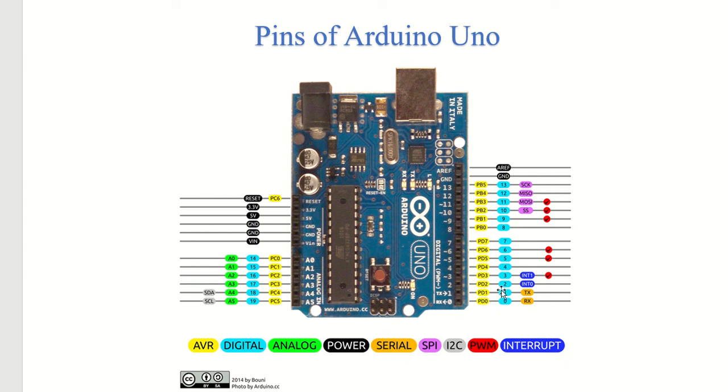So these pins cannot be used for digital input output, but only for serial input output. Serial communication is used to exchange data between the Arduino board and another serial device, like a computer or display or any sensor, any such kind of device. And you will find each and every Arduino board having such serial pins.